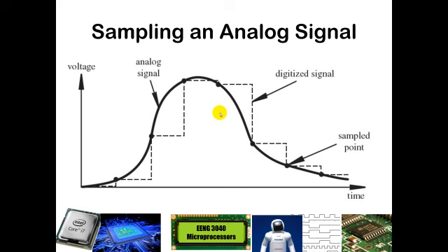This is showcasing a rather primitive digital representation with a fairly slow analog to digital converter, which is not fully capturing the essence of that analog signal. You get a bit of an idea here of what that signal looks like, but a much faster sampling rate would be needed if we wanted our digital signal to track our analog.